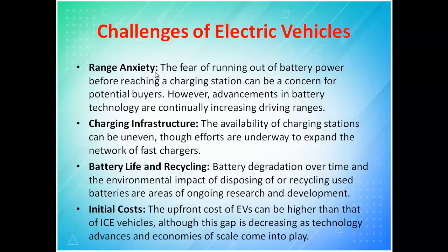For example, if we say 1000 life cycles, you can charge and discharge 1000 times, but when you do it properly, your efficiency will automatically increase. So you put your vehicle on charge, wait till it reaches 80 or 90%, and again you put it on charge only if it is less than 10%. Thereby you can increase the number of kilometers.